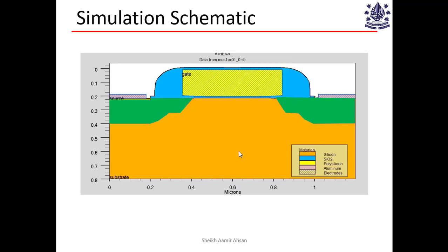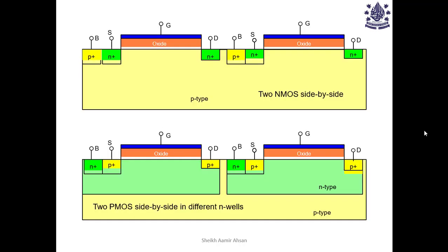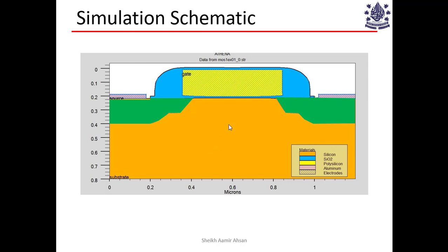So far, what we've drawn is these straight, sharp lines for these N-type regions, these body contacts, the oxide, the N-well. In reality, this is how it looks. This is a simple simulation of your MOSFET. As you see, this simulation has been carried out in Athena.